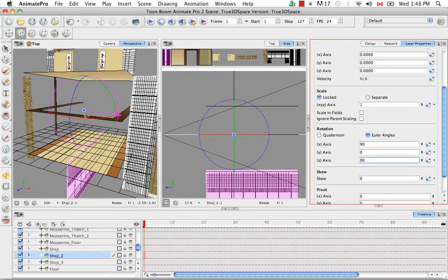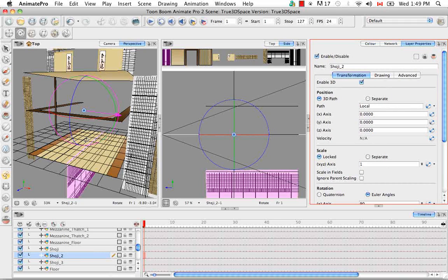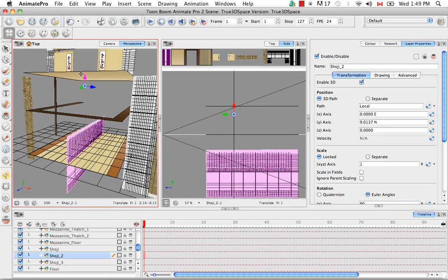And because it's rotating around this pivot point and not around its center, it's been lowered into what looks like the ground. It's been flipped over and around this pivot point. So now we have to do some adjusting for the XY position. So I'm going to use the Translate tool and highlight this red arrow and pull upwards.